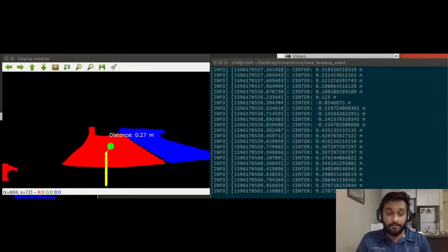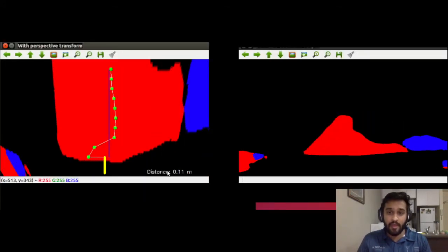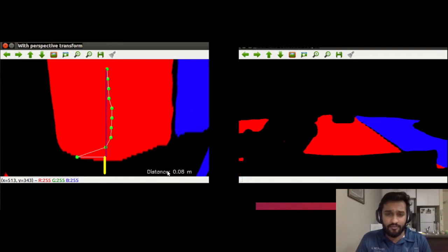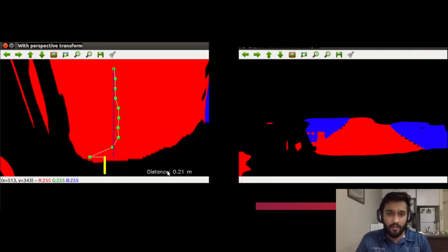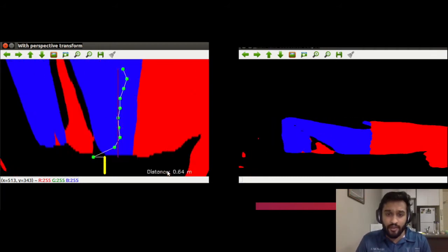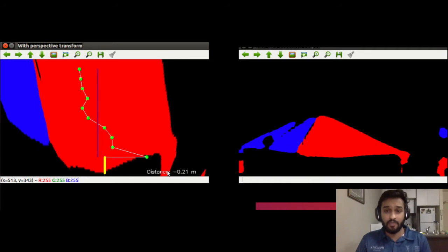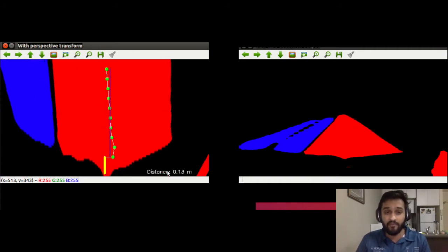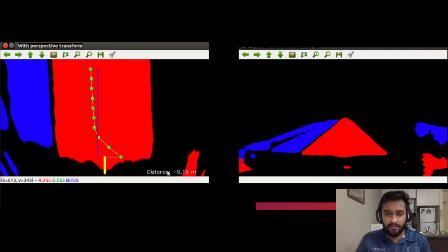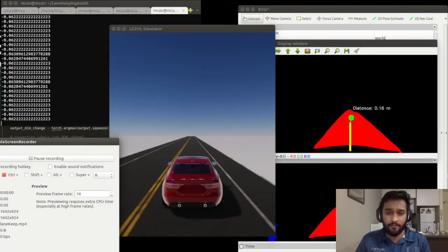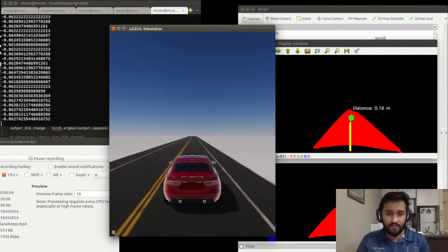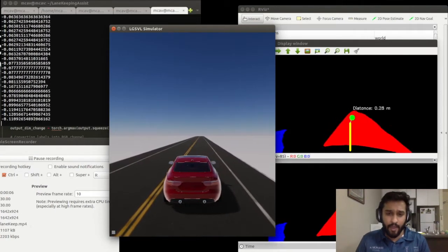Many vehicles today come with this driver assistance feature, and it's most effective for roads that have long, uninterrupted stretches like highways. Getting a little more into how it works, by first using our lane detection model's output, the lane keeping system first finds how far from the center lane the vehicle is. This information, which is distance, is then fed back into a PID controller, which outputs a steering angle to shift the car back to its lane center.